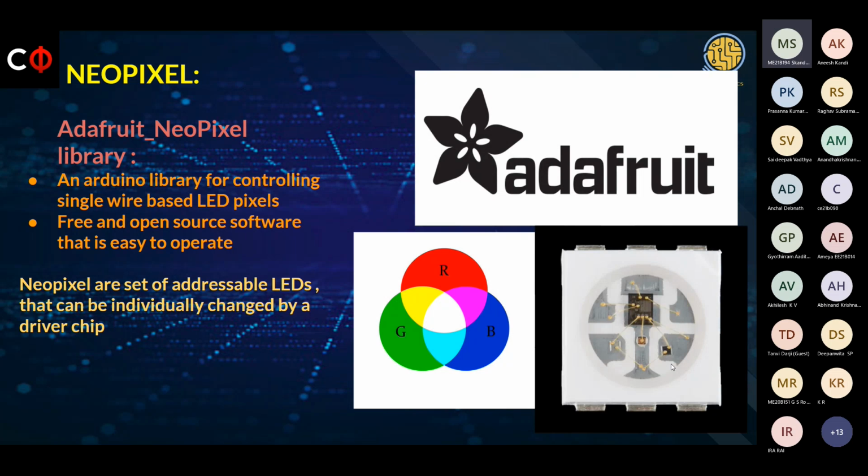What is the function of these ICs? These allow multiple LEDs to be accessed with a single digital pin by addressing each in a separate memory space in its RAM, and thereby accessing everything under a single wire.